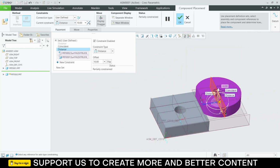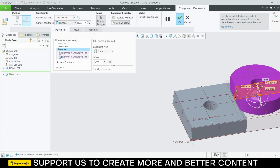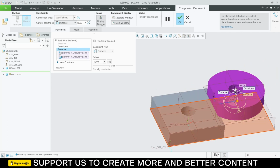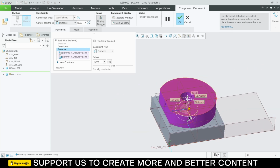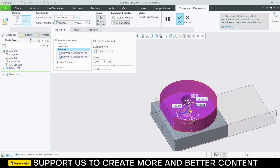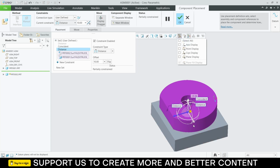Okay, and suppose someone says, hey, I want to move this forward or rotate it. How can I do that? This circle you see is called a gizmo. If I move this, I can move in a certain axis. The arrow basically helps us to rotate in a certain axis. Let's hide the planes because they are quite annoying.